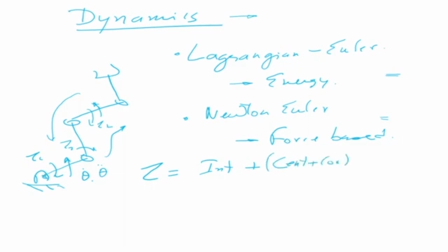So you can imagine that when one link is rotating on another link, suppose I put it like this, let me just draw two of them, one here and one here. When this is rotating with a velocity theta 1 dot, this could be rotating with a different velocity theta 2 dot. So this rigid body, which is this link, has another rigid body rotating with a different angular velocity. Basically it will be subjected to a Coriolis force also. It is like a body here, and there is something rotating on it. This is also rotating and that is also rotating, and because of the differential angular velocities, it will have a Coriolis force. Now there is a centripetal force because this is rotating.